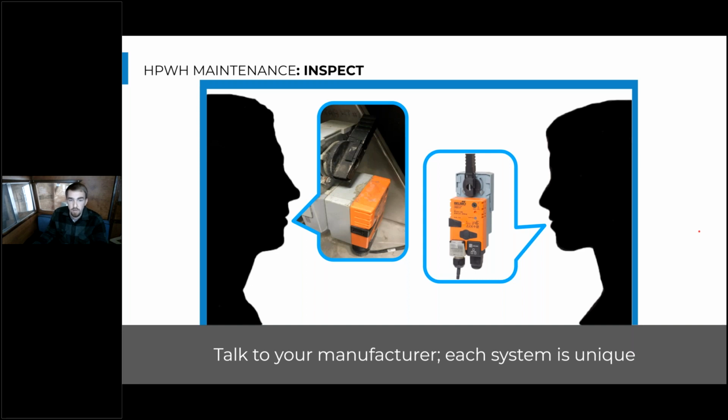And on certain heat pumps, you can easily check the actual refrigerant pressures. I was talking about how the pressure will rise on the high pressure side to drive a certain refrigerant temperature. But if the heat exchanger on that high pressure side is not allowing efficient heat transfer to the water, then that pressure will have to rise even further to push that heat more aggressively into the water.